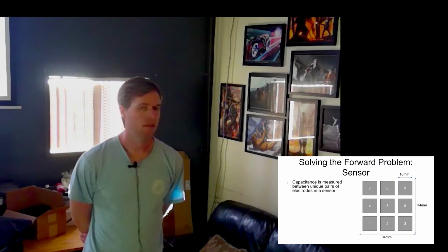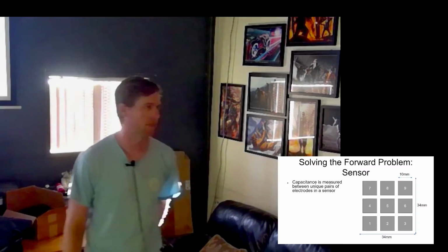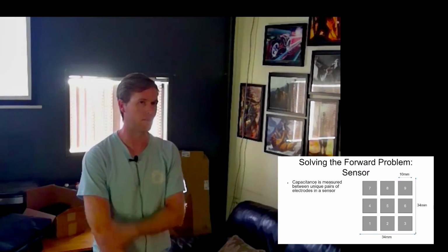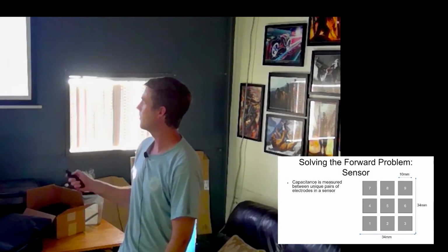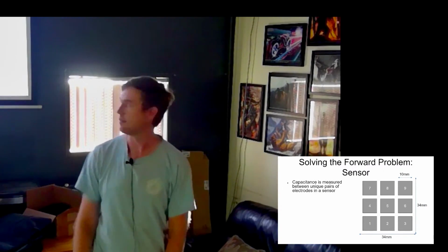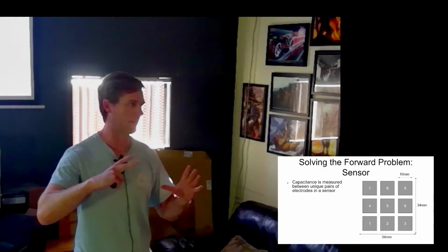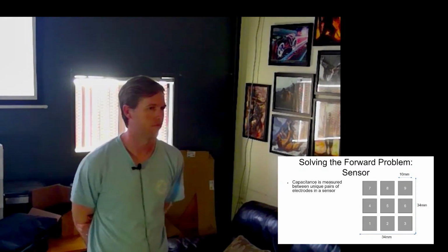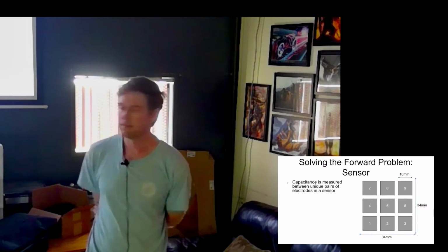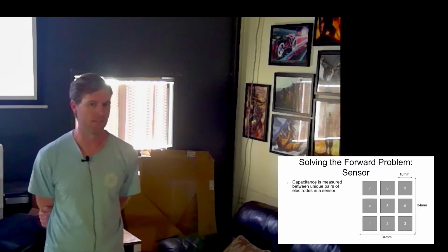Because I imagine the capacitance is pretty small here. Yeah, this is picofarad levels of capacitance, so it's a very, very small signal. If you can get away from using coaxial cables, it's definitely better. The problem is you run out of room because it's a pretty big PCB, it's like this big. I'm sure someone who's better at making these things could probably figure it out.